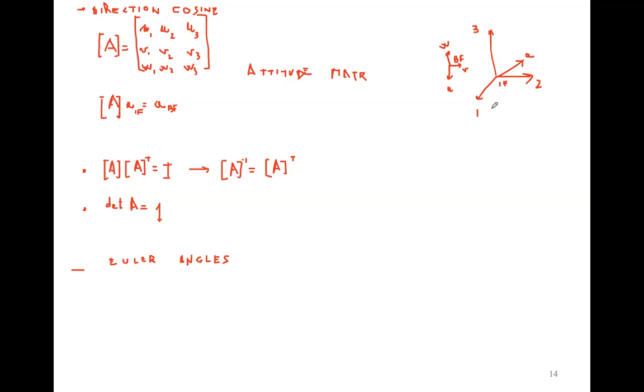But of course, it always depends on the geometry. If you approach singularities when you integrate, for example, the dynamical equation or the kinematic equation of the attitude, that will be really dramatic, and so you want to avoid that.